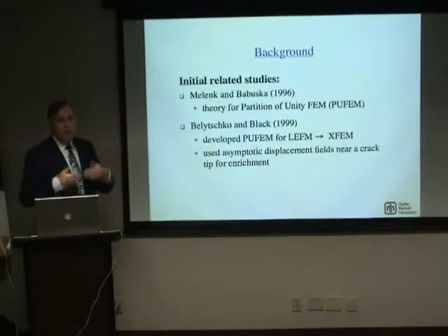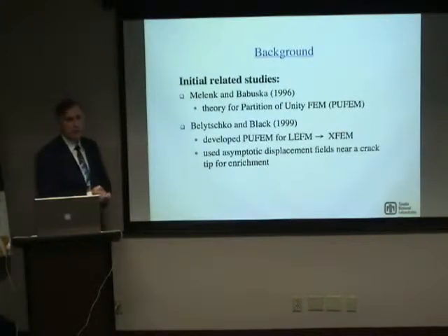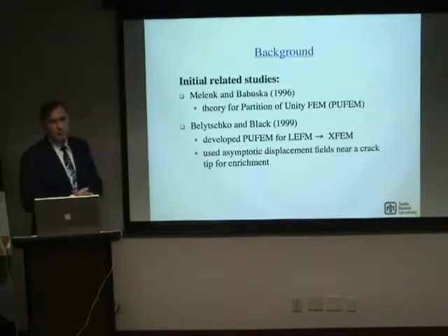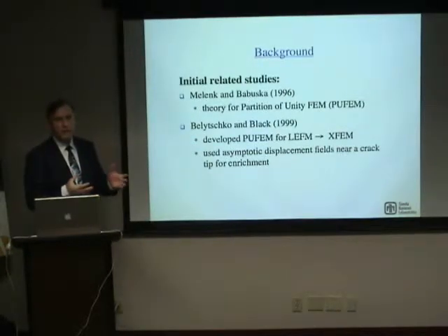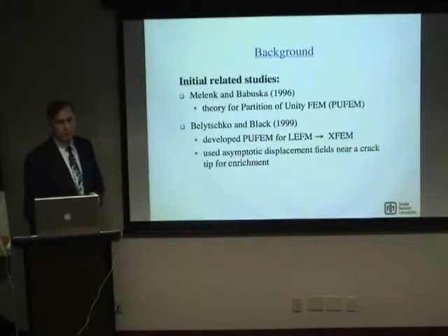Okay, first of all, you automatically get the continuity that you need, between elements, because you're multiplying it by the corresponding shape functions. But the other aspect is that you maintain the properties that we've come to all know and love in finite elements, in terms of having a sparse matrix for the representation of, say, a tangent stiffness or sensitivities and all. You maintain that same property because you're bringing it in a product form. So numerically, there are many aspects that carry over that we're used to with normal finite elements.